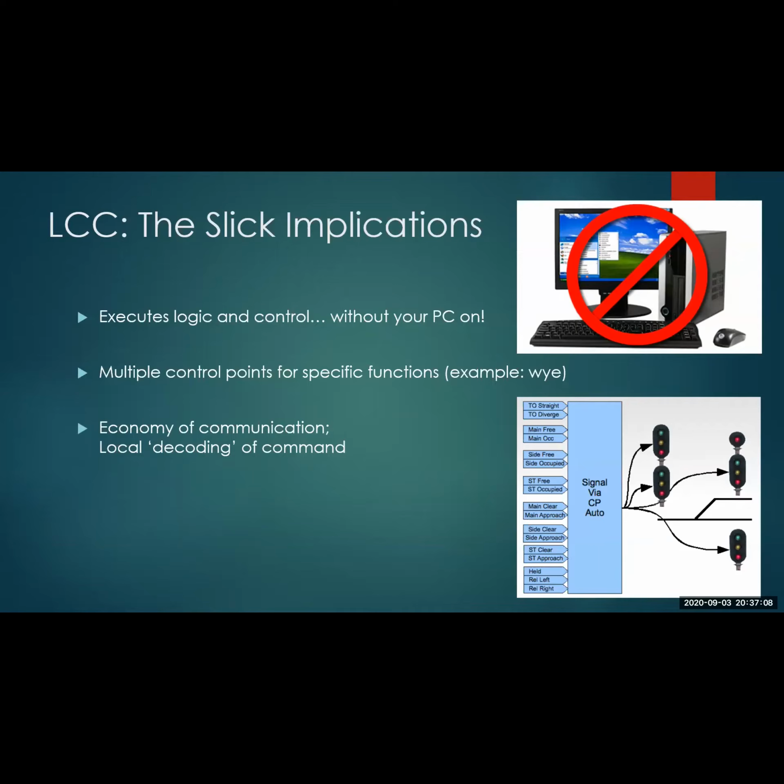And then the node itself will say, okay, slow approach from the west means at the node level, these indications for this lamp, these indications for this signal, these indications for this signal. So by sending out one general command to that node, the signals all can respond appropriately for a particular situation, medium approach or stop or whatever it is.